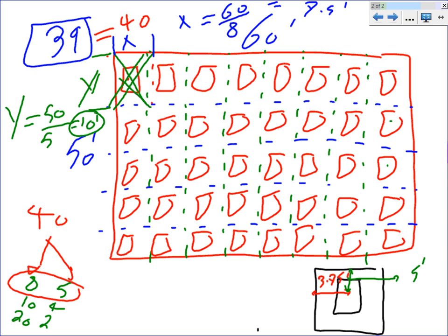It's like I said, x here is 7.5, and we find 3.75. If I can put 3.75, I can just make it 4 and start at 4. So leave one tile like this from here and move. Or if I can't, because it's laid out this way, say if it was half, there's a 2 feet here. If you add, this will be 6 feet, and I need to start at 4 to center of that. So you might have to shift your fixtures to a certain dimension, just to match your grid.